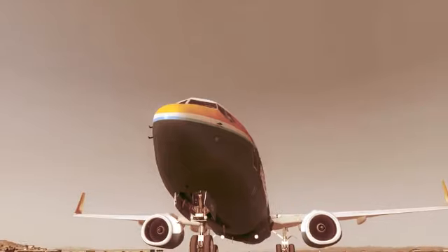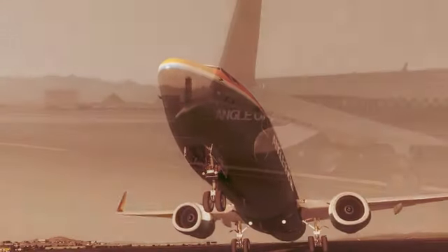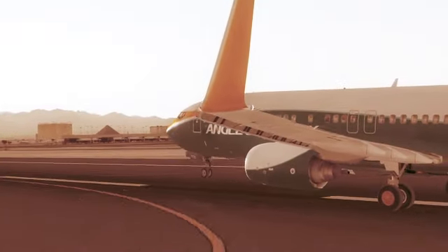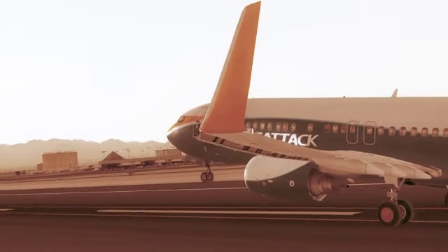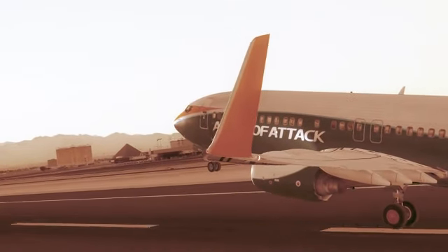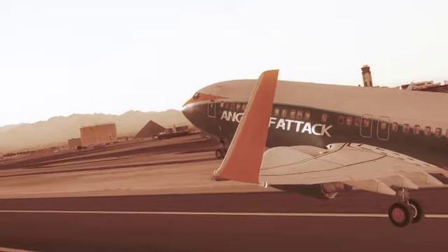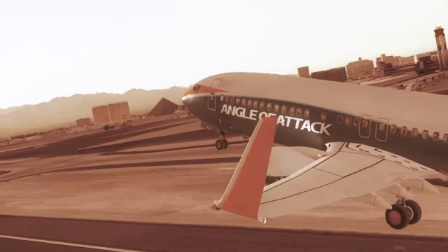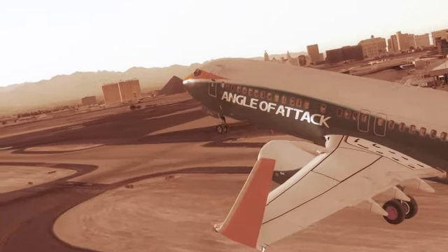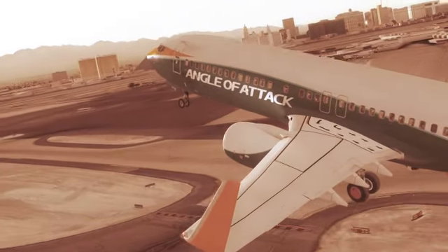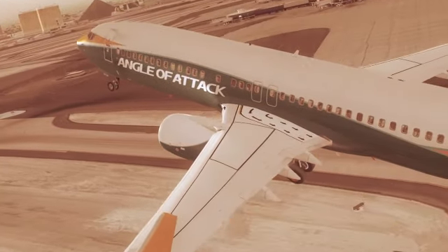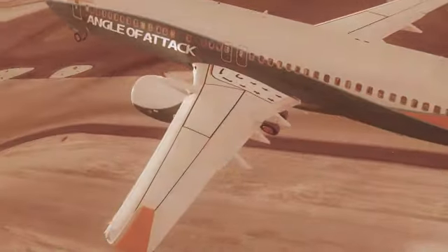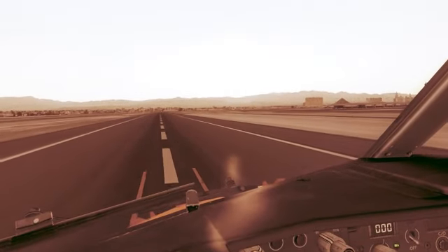Going back to engines, when bleed air is extracted from them, part of the air that enters the fan is no longer producing thrust. Instead, it is being ducted out of the engine for pneumatic power. This means that the engine would not be delivering its maximum thrust capacity, and there are situations where this condition may be conflictive, such as during takeoffs from short runways.